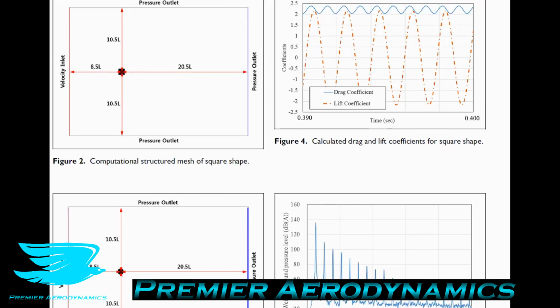So this is important because currently pretty much all Lattice Boltzmann methods, maybe not PowerFlow, I'm not too familiar with PowerFlow, but every other Lattice Boltzmann software that I've come across uses structured meshes. An artifact of the simple approach to implementing the Lattice Boltzmann method is you need to have each point equispaced from each other. So you get a structured mesh. And they say here the finest voxel size was 0.2375. Again, the voxel size is the equivalent of the cell size.